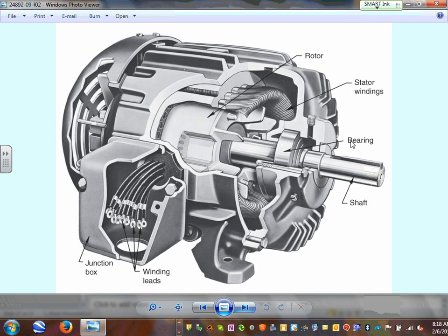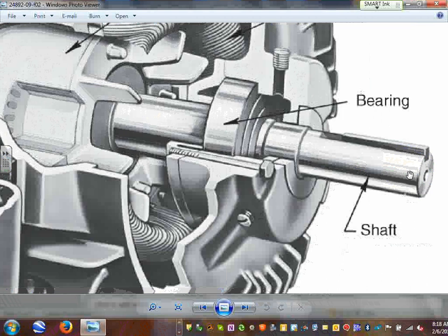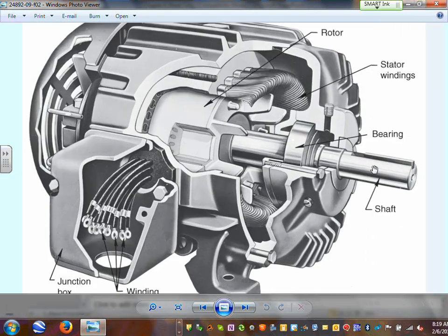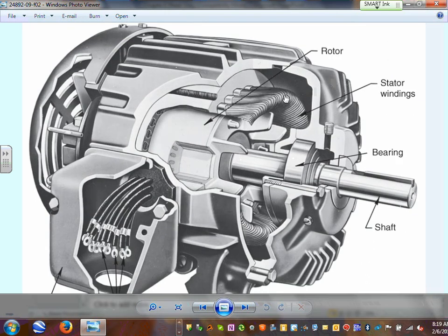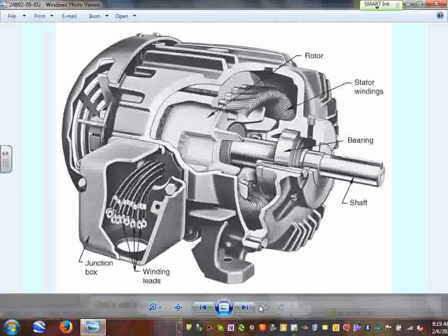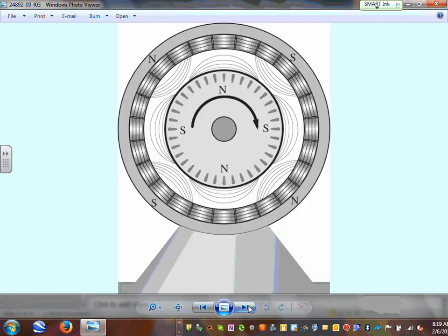Here's your motor, guys. A couple of motors. The motors have a shaft. That's probably the most important thing here because you capture torque. You energize a coil, induce voltage into the rotor, and create a rotating magnetic field that drives this rotor to move. Of course, you have to facilitate mechanical movement by having a bearing here. The stator winding is what you energize, and here's all your connection right here to get your motor. You're looking here at 30 to 40% of every electrical power system in any building. That's the heart of it, the chiller, the pumps, and all this good stuff.